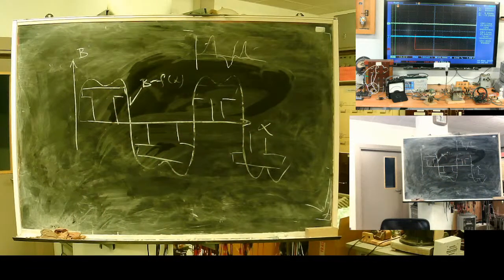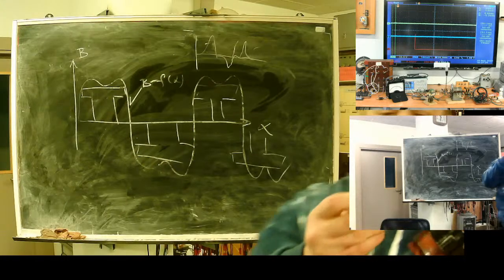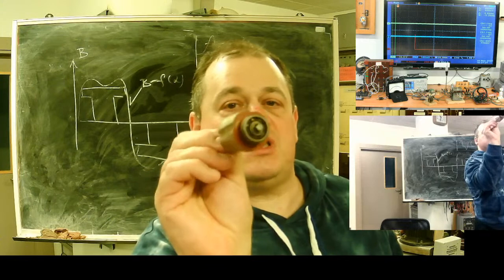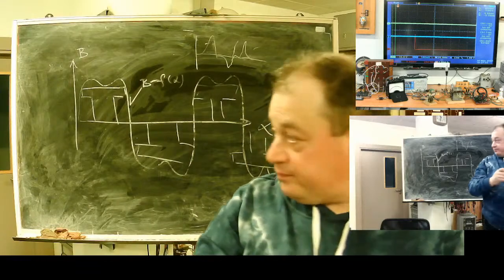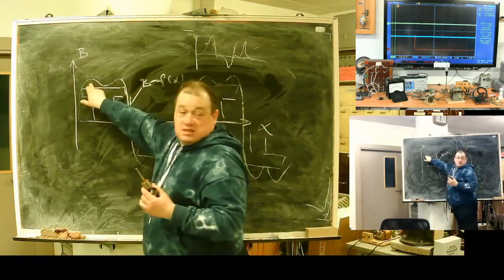So without some measures, such kind of generator will produce not sine but something else. Here is a small one. This one is polyphase, three-phase. See the design of the rotor? You see this channels between poles are not straight but form a kind of spiral, like a barrel of a gun. It's done to smoothen these parts.